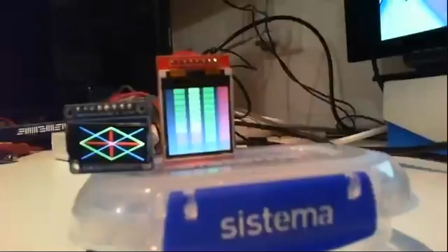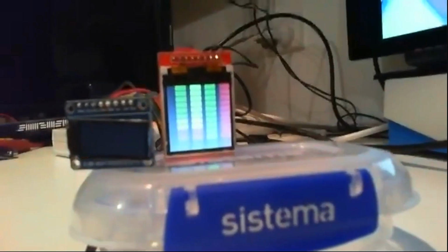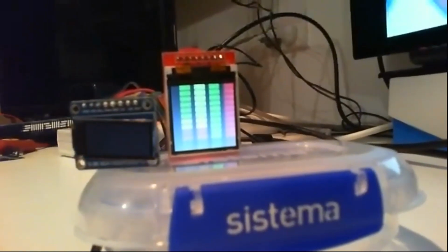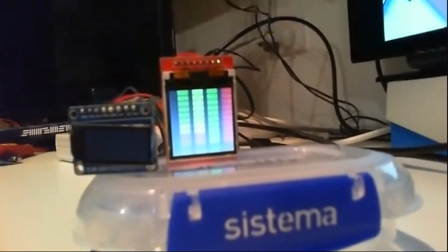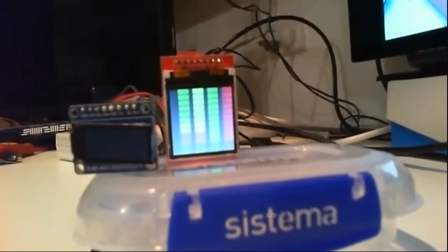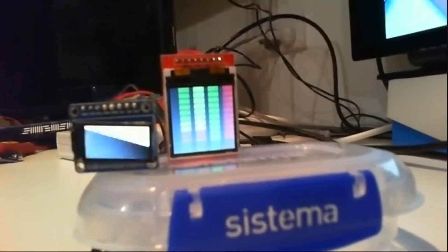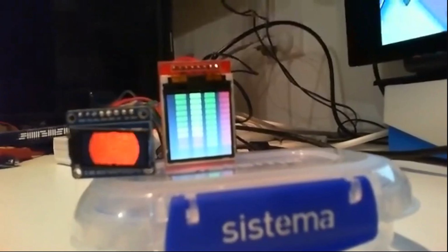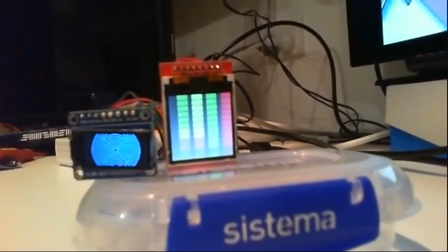So it's a little bit slower if you just want to set individual random pixels. It seems like it would be better just to maintain the bitmap in the P2 and then just update the whole thing. That's what I've been doing, and it's a lot quicker, obviously. You're not sending out as much data. And because you're using the hub memory as that frame buffer, you've got a lot more powerful means of doing scrolls and color swaps and this sort of thing.